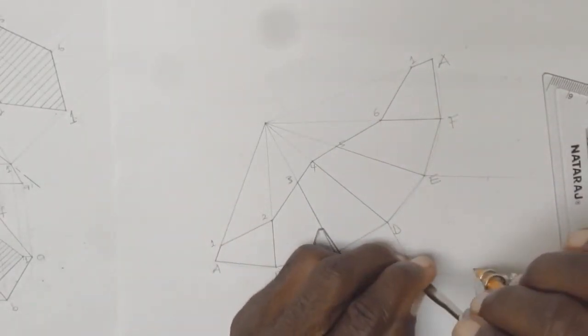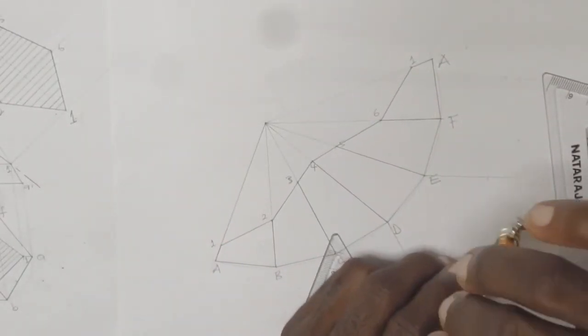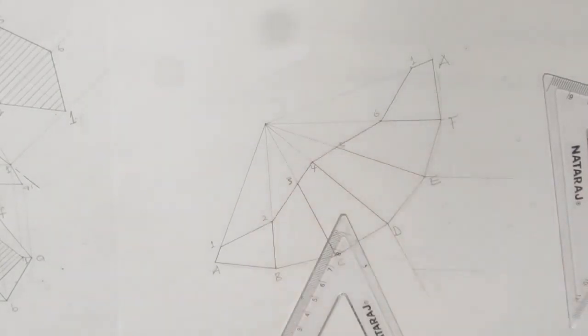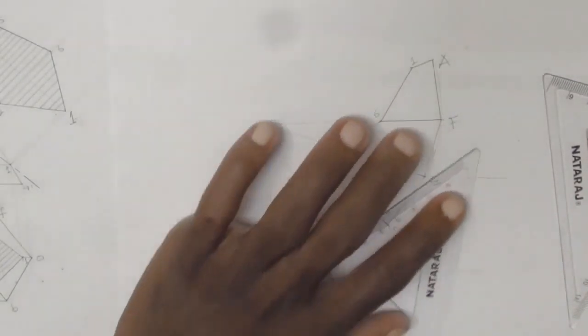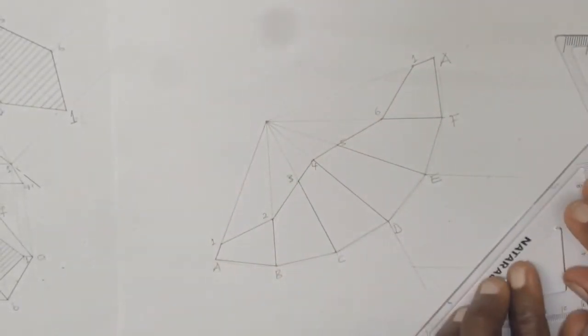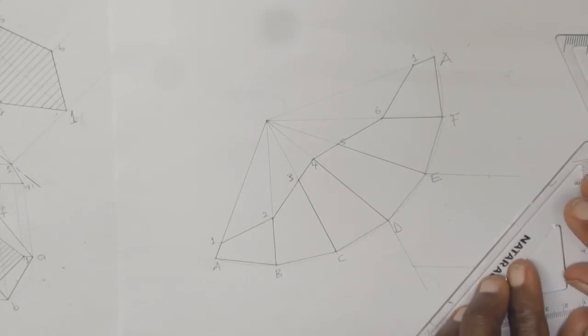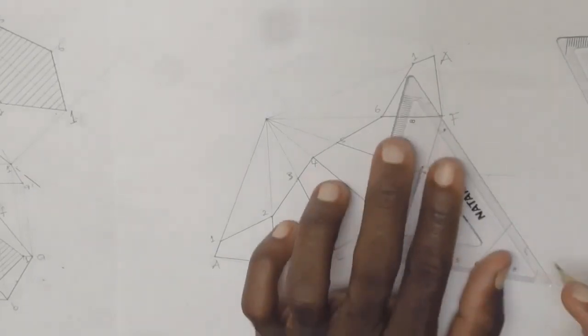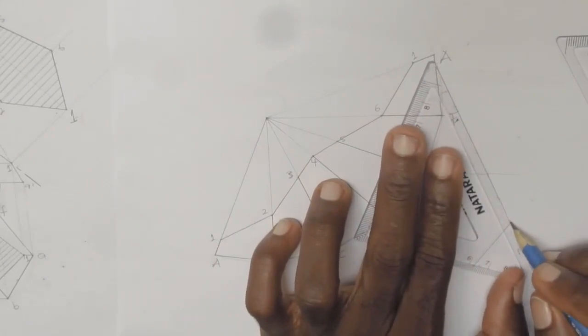Then I mark. Then from that point, I don't need to draw. I can just use the compass with the radius 30 from the end of point there to draw two arcs that will intersect. Then I will connect the ends of these lines to that point of intersection.